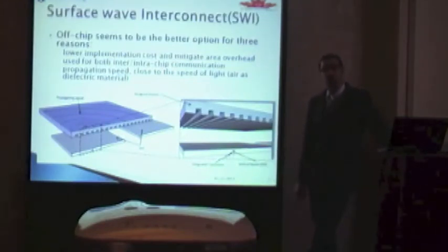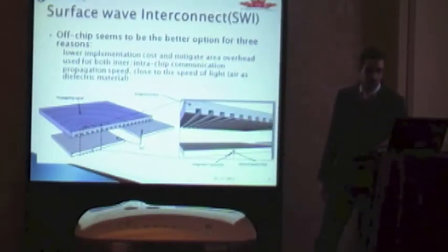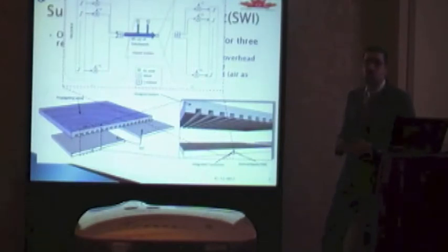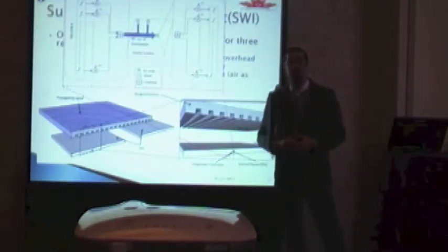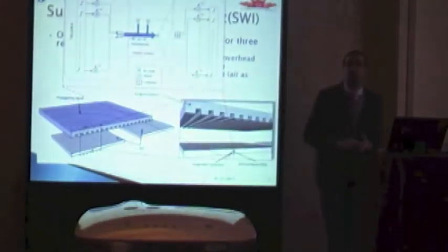We adopted the one proposed by Chang in 2011, which is a transceiver used for waveguided signals. Also, we need to implement a vertical diode that can be realized through the technology of through-silicon via to achieve the right launching of the signal to the surface. And the structure of this transceiver, as you can see here, is based on FDMA modulation, and we choose to have these 128 sub-channels in order to achieve transmission of one flit per cycle.